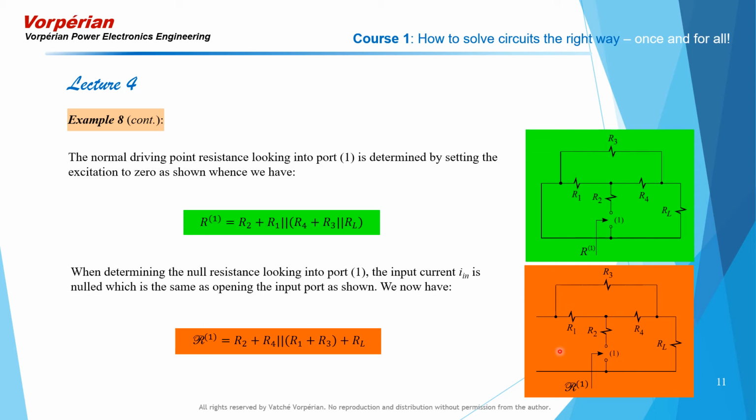The response in this case, remember, is that of the input admittance function, which is the current coming out of the excitation connected here, the voltage source. And when we null that current there, we talked about in the proof of the extra element theorem that that is equivalent to opening that junction there, that port there. Maybe you want to go back and again review that.